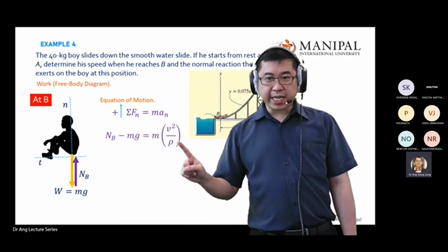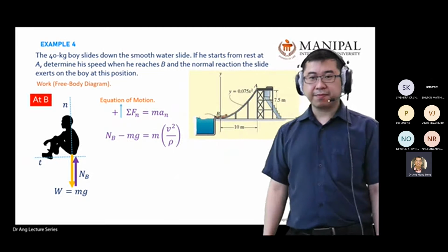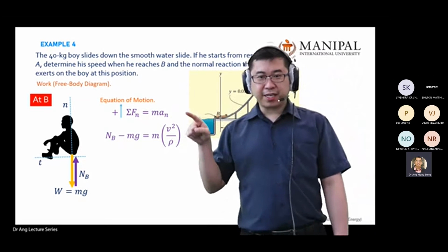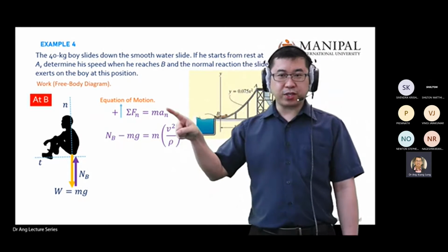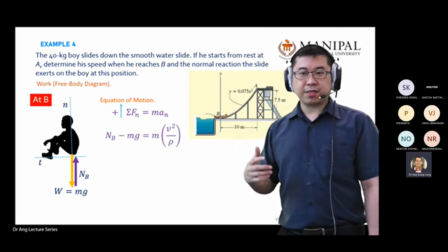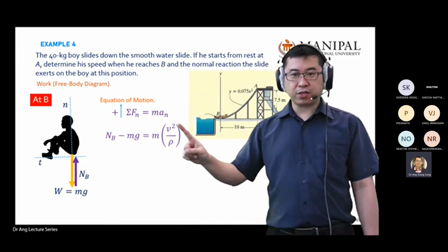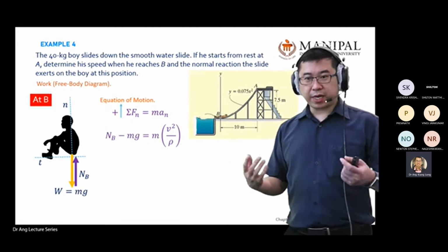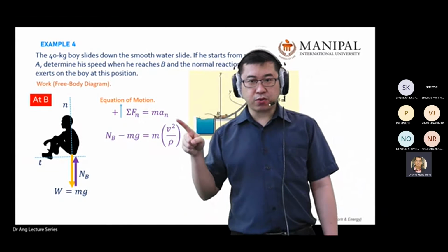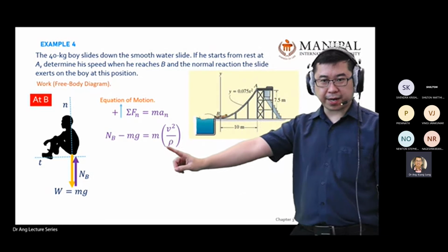And you know that there's one equation specifically to calculate the radius of the circle, right? You have to recall it. It comes as a package, meaning if you see curvilinear, you're sure you need to calculate an equal to v squared divided by rho. Sometimes your lecturer is very kind to you and will give you the normal acceleration straight away, so you don't need to calculate this one. However, when it comes to the final exam, sure we want to test whether you know there is an equation to calculate normal acceleration. So sure you need to use this one, v squared divided by radius.